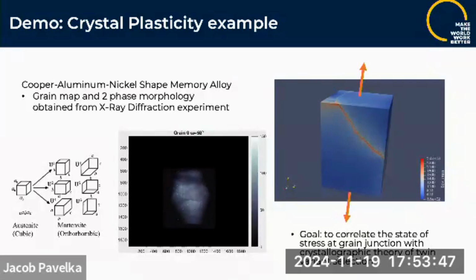Are we trying to find this only with a single crystal or in polycrystals? If there are multiple grains, maybe we need at least 5 slip systems to activate if we need to deform a grain. So are we looking at that too? Yes, these twins are something different from slip systems.